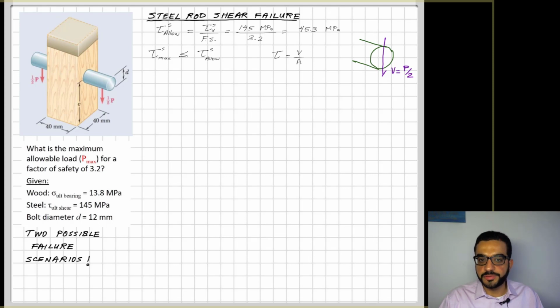It's double shear, right? We have here P is split on both sides of the member, and there is one P coming from the wood applied on the bar. So kind of we see two shearing actions happen on both sides of the bar here. We're analyzing one of them, and this is why we have half of the force applied here, P over 2.